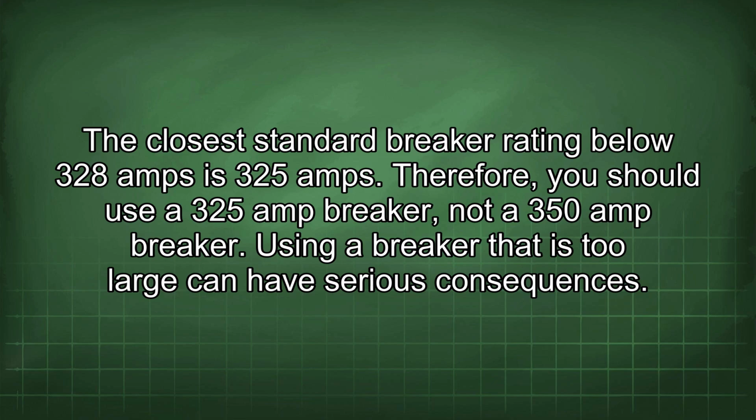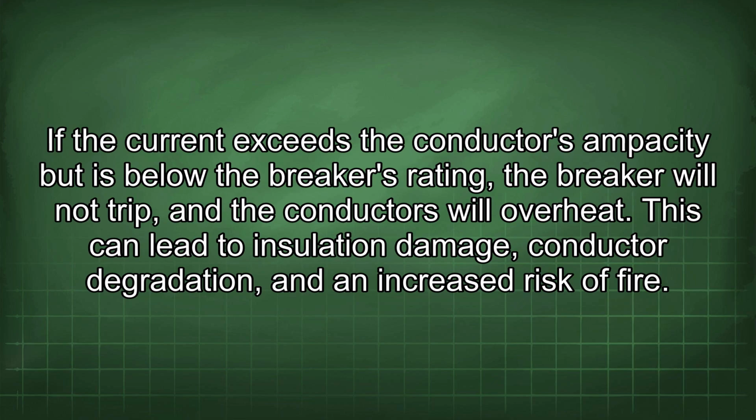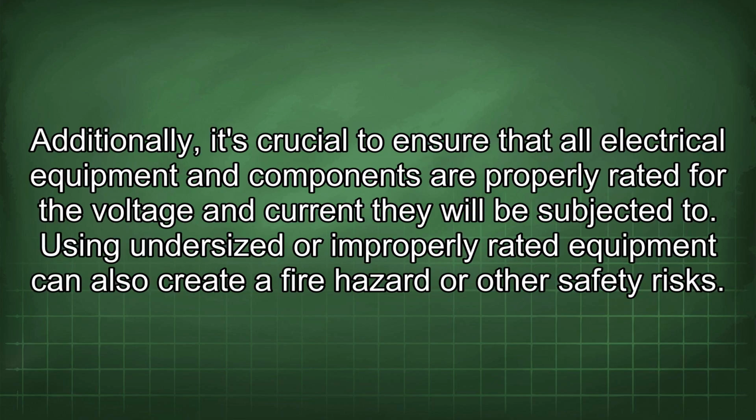Using a breaker that is too large can have serious consequences. If the current exceeds the conductor's ampacity but is below the breaker's rating, the breaker will not trip, and the conductors will overheat. This can lead to insulation damage, conductor degradation, and an increased risk of fire. Additionally, it's crucial to ensure that all electrical equipment and components are properly rated for the voltage and current they will be subjected to. Using undersized or improperly rated equipment can also create a fire hazard or other safety risks.